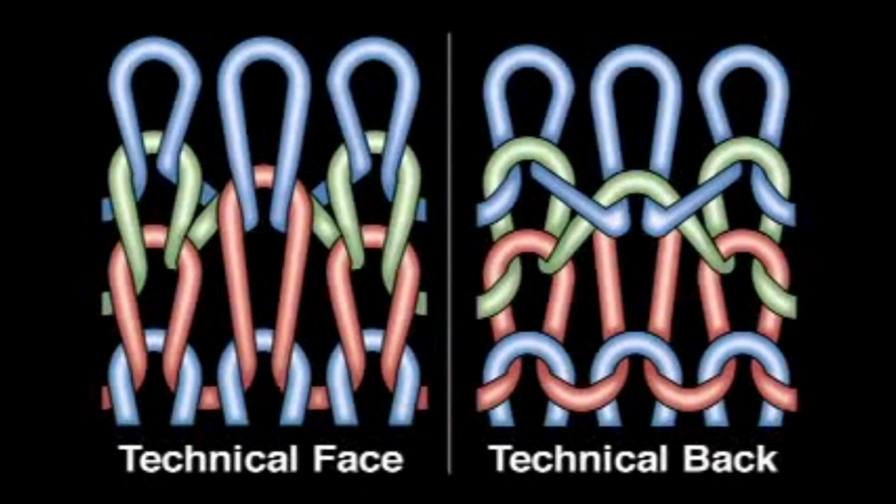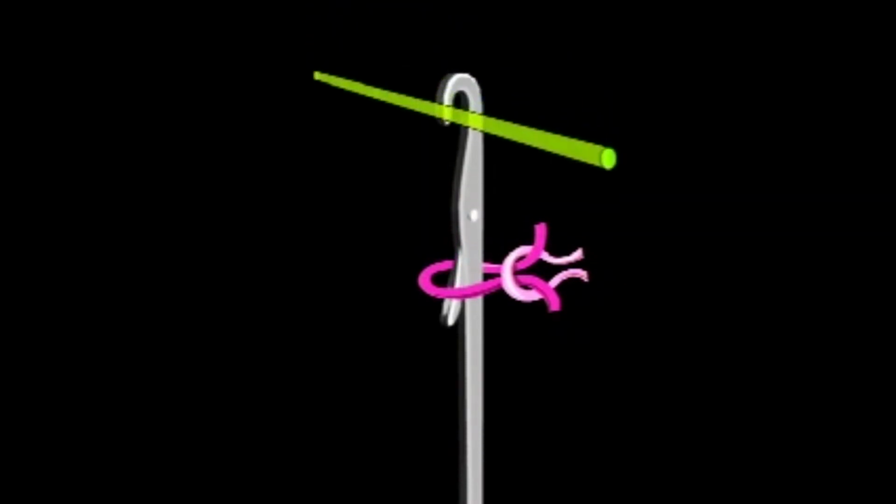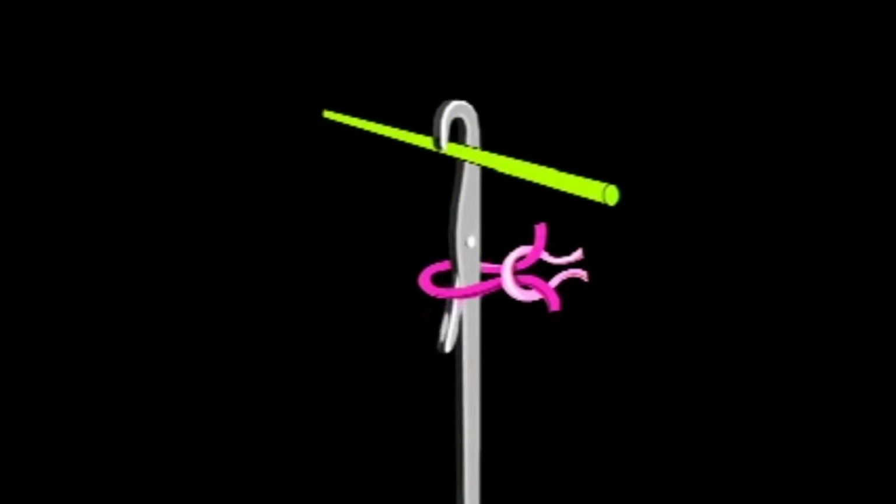How is a tuck stitch made? During the tuck cycle, at feed 1, the needle moves up from its rest position and the old stitch that has been formed is held and not allowed to clear the latch. Yet the needle moves up far enough to grab a second yarn, which is put into a tuck position. Both yarns are then kept at the rest position.